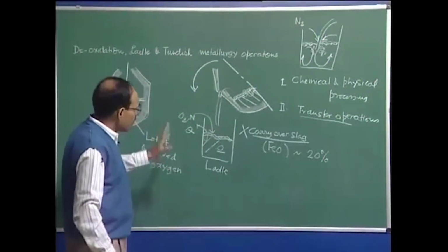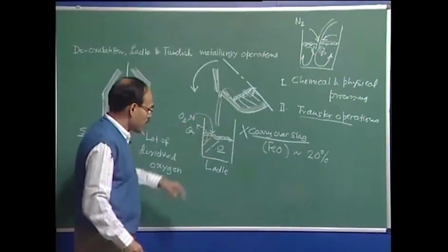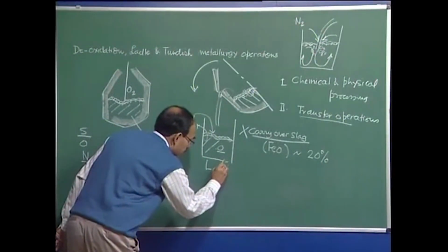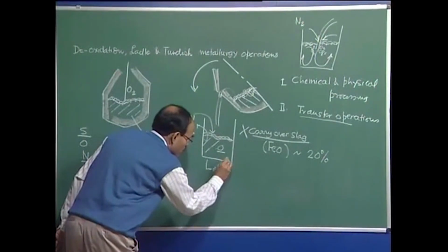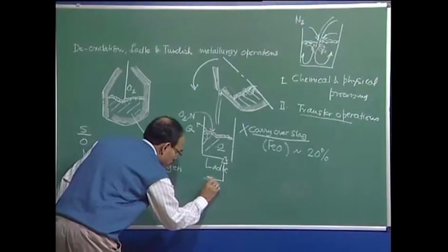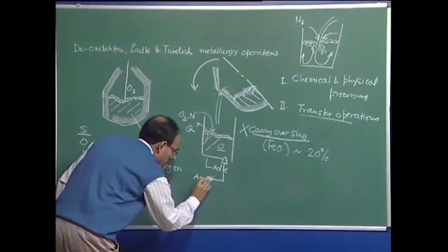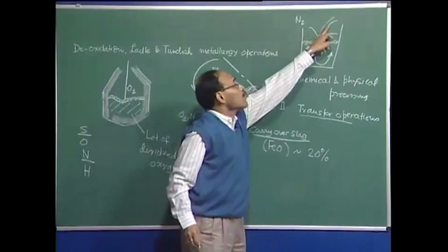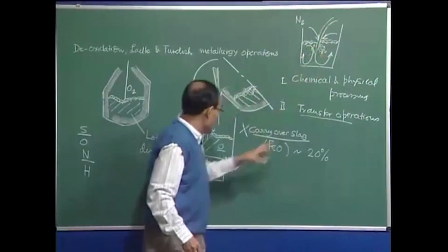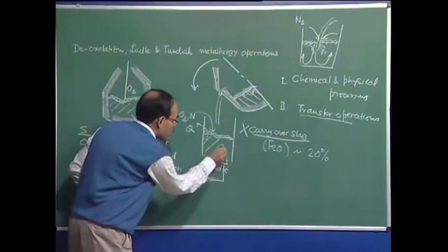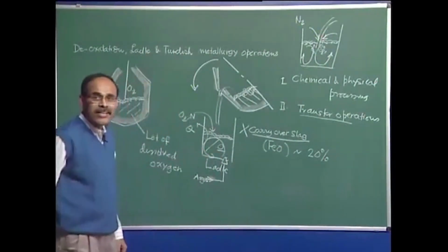So that's why the moment we start to pour molten metal, we will see that we have a porous plug which is located here at the bottom, through which we are going to inject argon. So even when the intensity due to the impinging stream dies down, this argon being injected through the porous plug will give rise to a reasonable amount of stirring in the system.